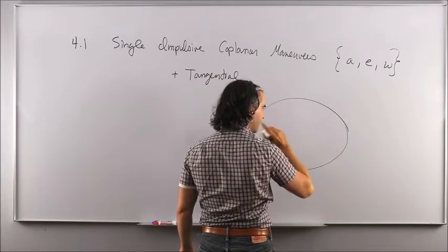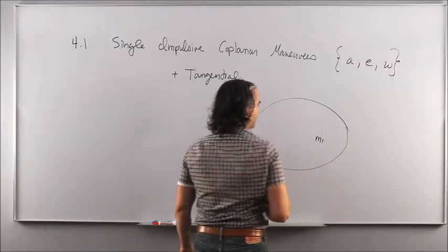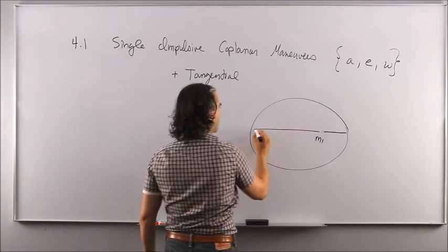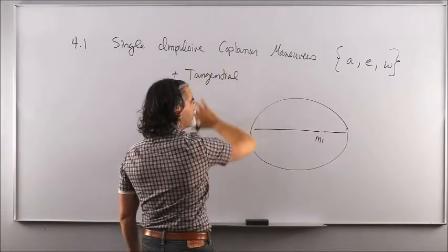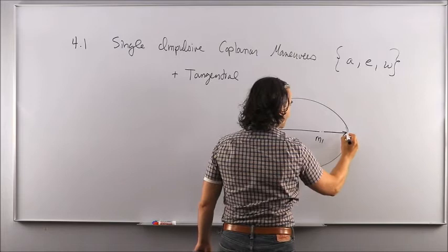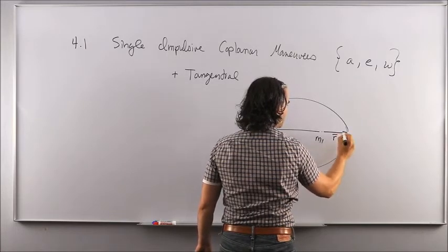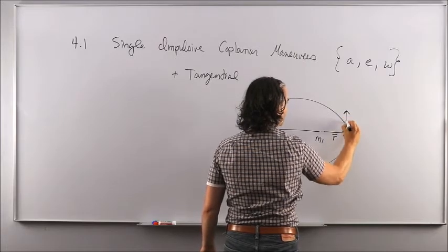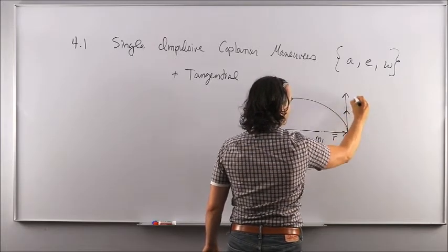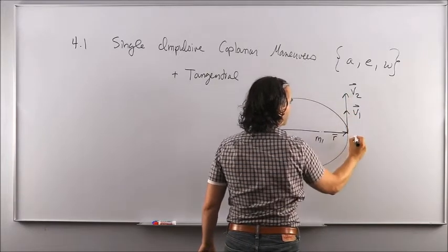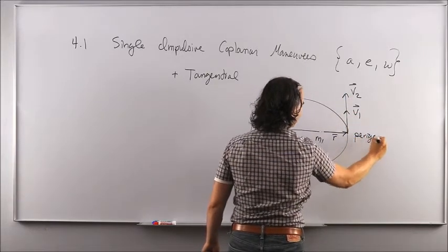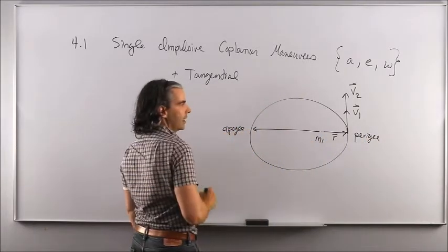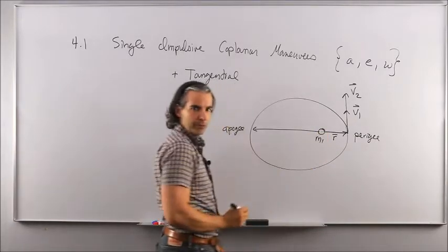Turns out that along an elliptical orbit, there are only 2 points then that we can apply maneuvers if we want to consider all those assumptions, because both orbits need to intersect and they need to share the same direction of their velocity vectors. Turns out that, again, along the elliptical orbit, only the perigee and the apogee are valid locations then to apply a delta V maneuver.